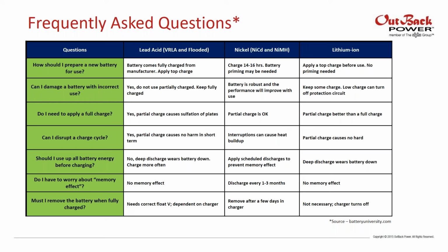Should you use up all the battery energy before charging? Lead acid, absolutely not. If you go to 100% depth of discharge, you will permanently damage that battery and it will need to be replaced. Lithium, you can go to 100%, and again, consult your manufacturer specs.